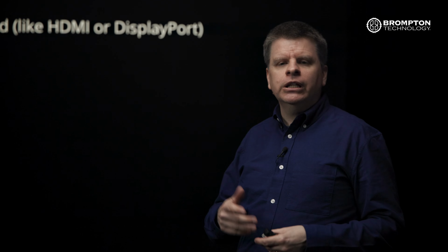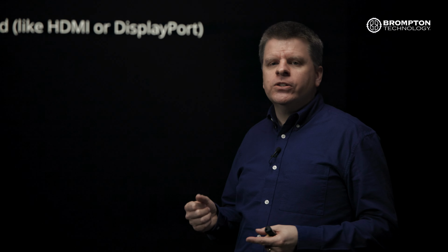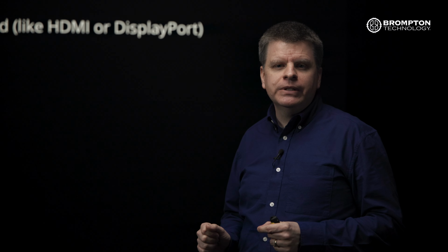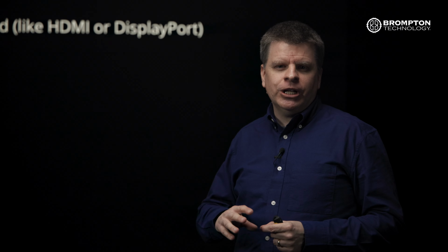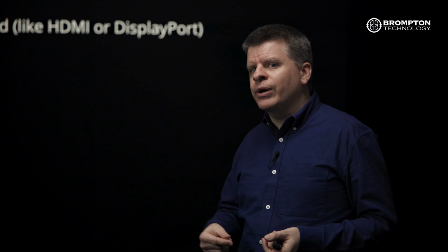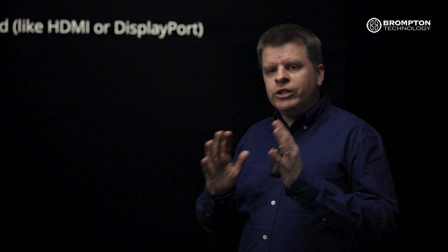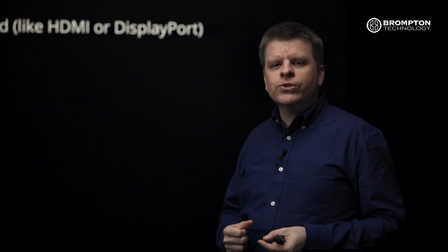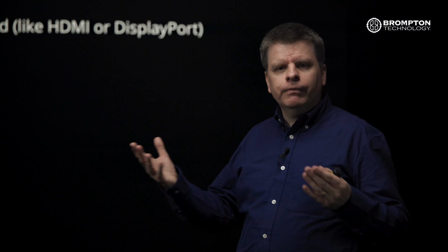SDI works a bit differently. I kind of call it a blind transmitter. So essentially an SDI source will just decide for itself, this is the video signal I've got, this is what I'm sending. And there is kind of no back channel. So it doesn't matter what's at the other end of the cable. It doesn't actually even matter whether the other end of the cable is connected or not. We're just going to keep transmitting a signal down that cable. And provided the receiver is compatible with the source, okay, great, we're going to be able to show you that video signal.